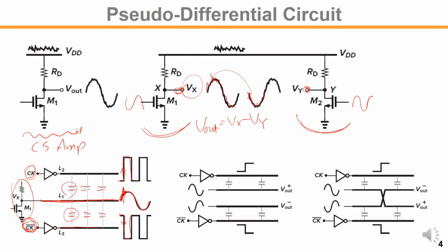But to make this work, we have to make sure that CP1 and CP2 are the same. Another case, for example, in differential signaling: the noise coupling signal is running nearby, right next to our signal.